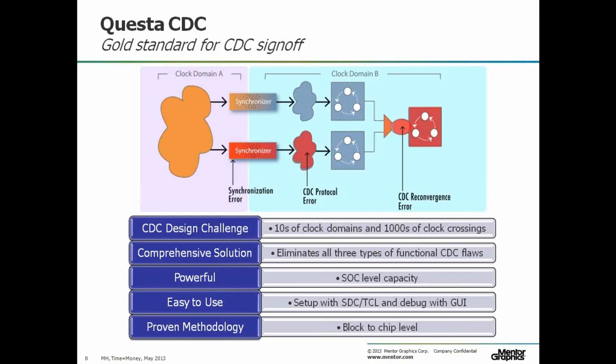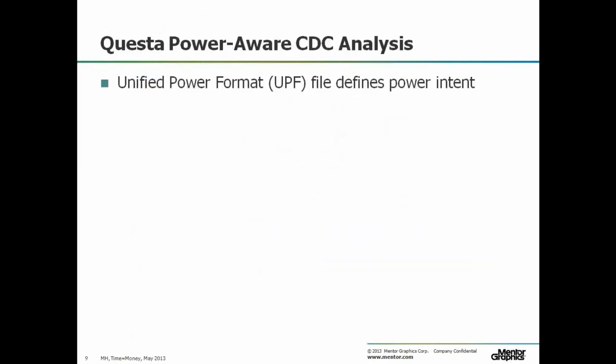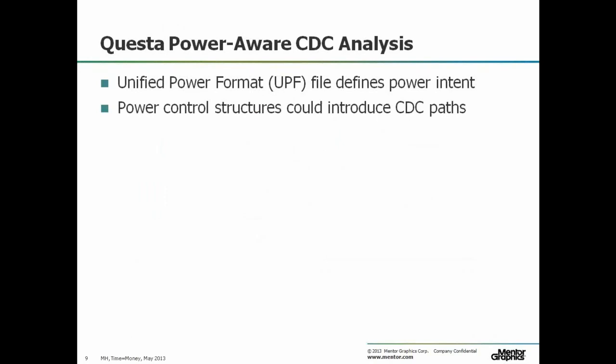And again, you can use formal analysis to find these reconvergent paths to check that you don't have any issues there. And then you can extend the CDC analysis into the power domain too. Many of you will be using UPF to describe your power intent, your power islands, and you can verify that in simulation. You can use formal techniques to help with verifying power controllers and suchlike.